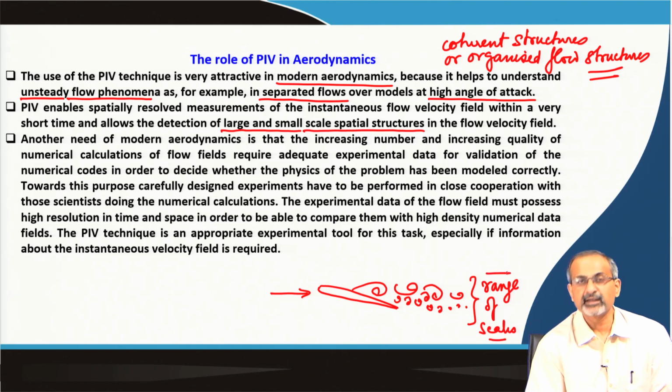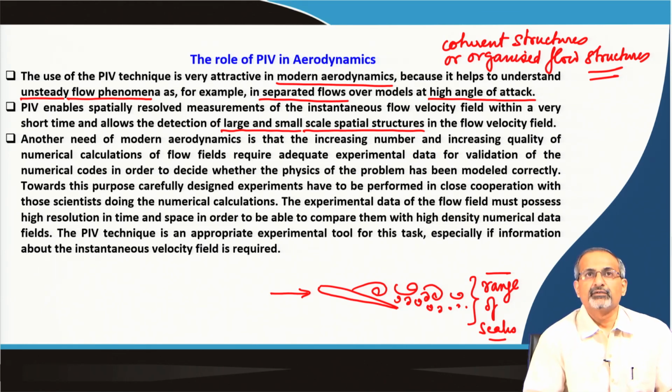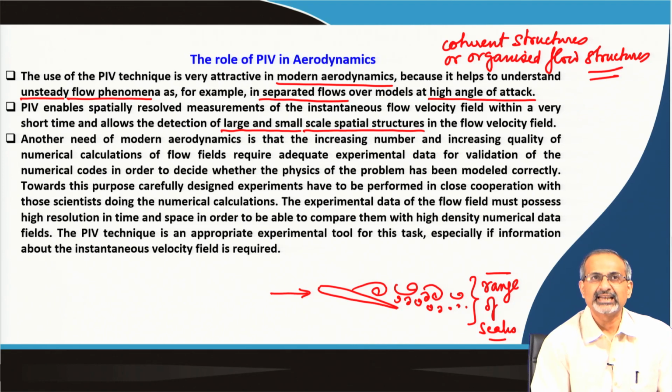and this is an inherent characteristic of a turbulent flow field, where a repertoire of large, medium and small structures coexist. So, a PIV system has the challenge of spatially resolving all these structures. Additionally, if they can be resolved with very fine temporal accuracy, then that will be an extremely ambitious goal fulfilled on both ends, spatial as well as temporal.